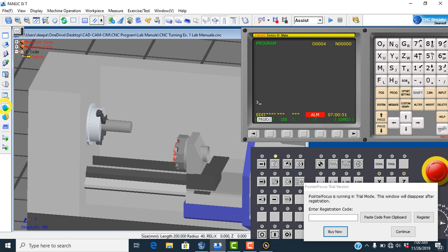Now this is for workpiece setup. You can set the stock size, turn around the workpiece, coolant adjustment that I showed in the previous class, and the rapid positioning of the tool. Now this is for making the rapid simulation. If there is a lengthy CNC program and you want to see the whole simulation of this particular program, in a few seconds you can see the whole program simulation.